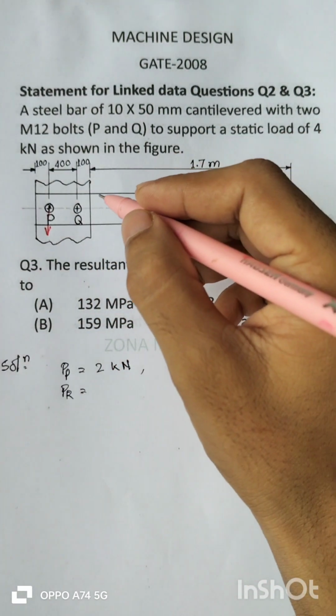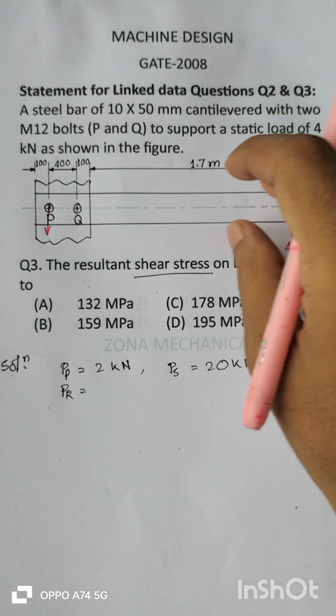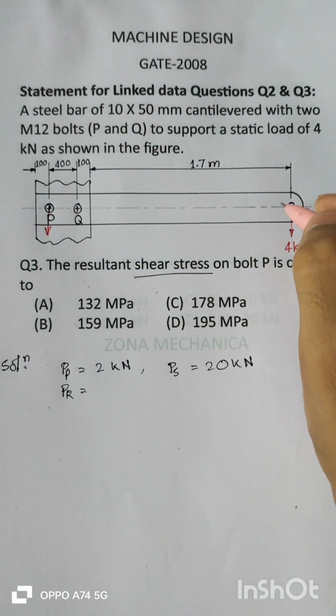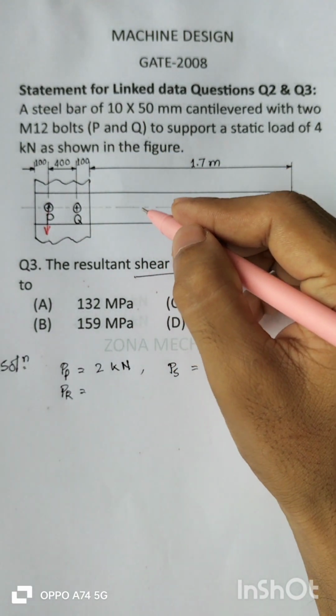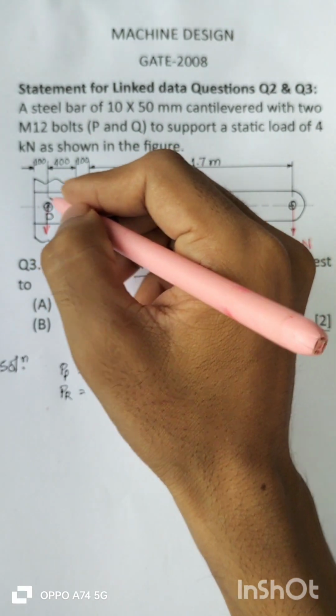But the secondary shear load is occurring due to the moment developed due to this force, that is the force into this distance. So the clockwise moment will be generated, and due to that moment the secondary shear will be acting.